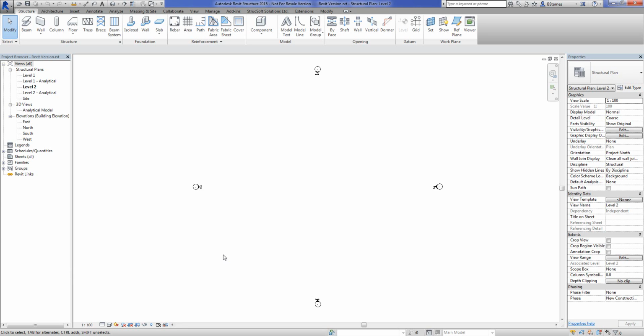So if I don't want to change anything, I've got to try to find that exact version of Revit that was used to create that file and open it using that version of Revit. It takes time. We're launching a whole bunch of instances of Revit in the hopes of finding out which of them produces the desired effect on opening this project. And I'd say there's an easier way to do this.